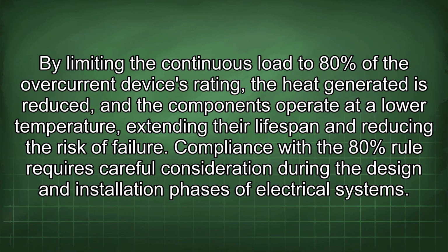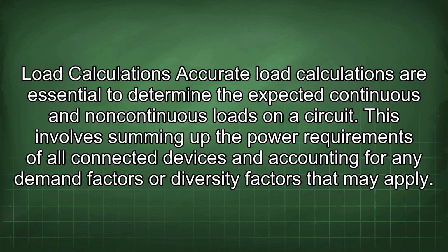Compliance with the 80% rule requires careful consideration during the design and installation phases of electrical systems. Load calculations. Accurate load calculations are essential to determine the expected continuous and non-continuous loads on a circuit. This involves summing up the power requirements of all connected devices and accounting for any demand factors or diversity factors that may apply.